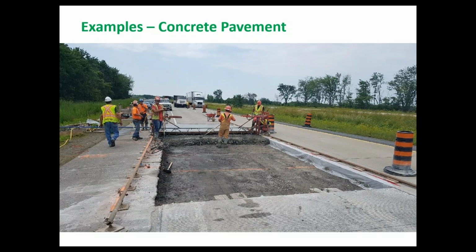Concrete pavement is also a very unique application for these wireless maturity sensors. You're dealing with remote conditions. This was a piece of highway pavement that had to be repaired almost 100 kilometers away from the lab. So that would take them obviously a long time to pick up the specimens, the field cure cylinders, and go back to the lab and break and give the results.